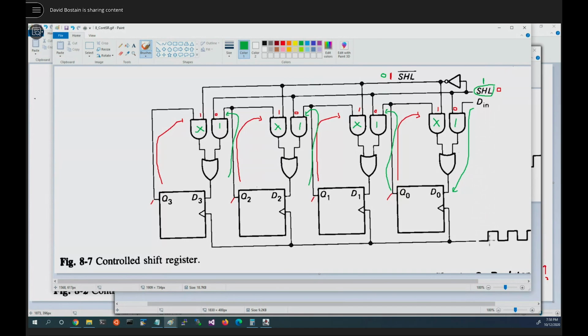And we have to ensure that in both those cases the clock here is long enough, which it will be because we wouldn't have designed the circuit without it being, but it's long enough that we can eat up all that 25 nanoseconds. Plus we need to eat up another 20 to handle when it goes low again. So that's kind of a tour of how those guys might be hooked up. You can imagine many more elaborate ways that all this stuff could be hooked up.